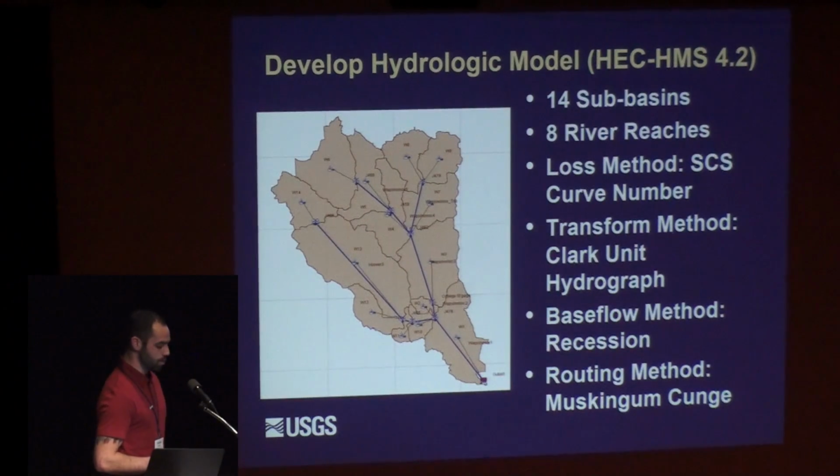And then also, I need to know the discharge information so you can calibrate your hydraulic model so you get the right amount of runoff to match whatever discharges we're getting at these gauges.